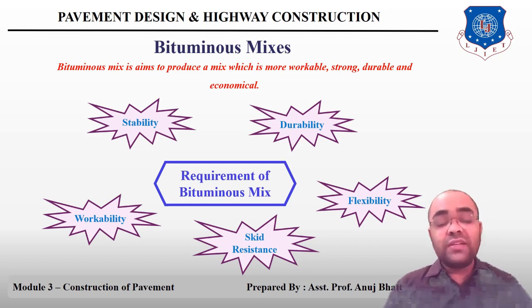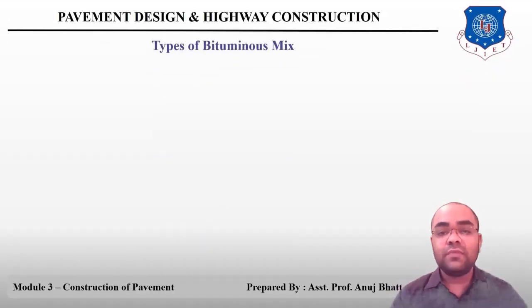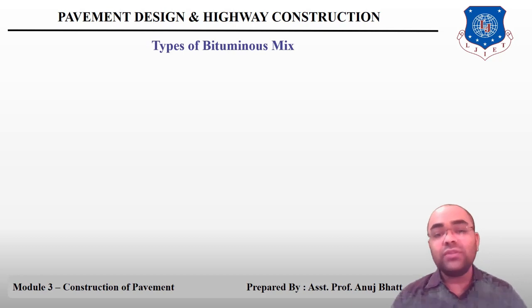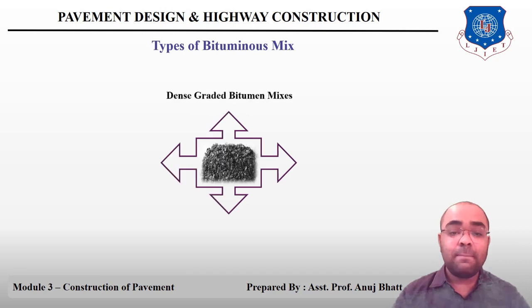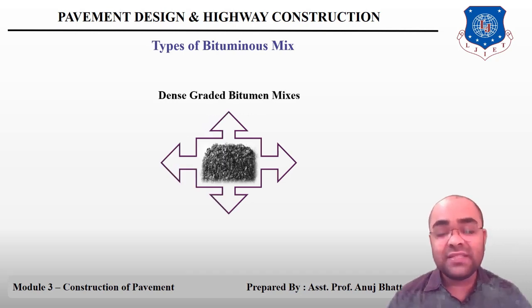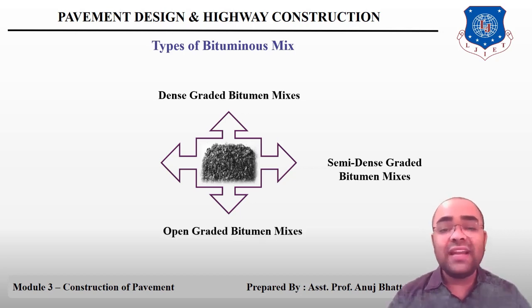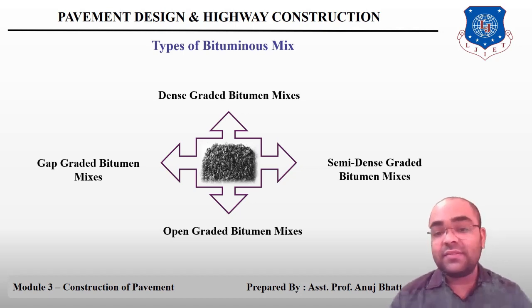Now let's talk about the different bituminous mixes. There are various types of bitumen mixes with aggregates for pavement construction. Based on the nature of the gradation, they are classified as dense graded bitumen mix, semi-dense graded bitumen mix, open graded bitumen mix, and the last is gap graded bitumen mix.